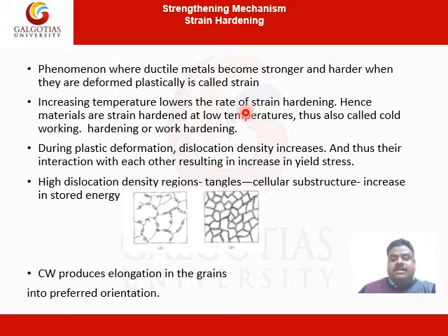Generally the materials are strain hardened at low temperature, so that's why we call it cold working or work hardening. During plastic deformation, the dislocation density increases.